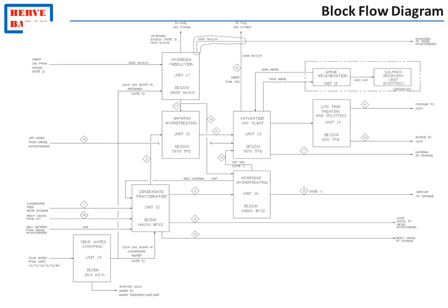Once the design of all these process units has been done, process is able to gather the consumption of all of them in the various utility fluids, such as cooling water, steam, fuel gas, and so on.